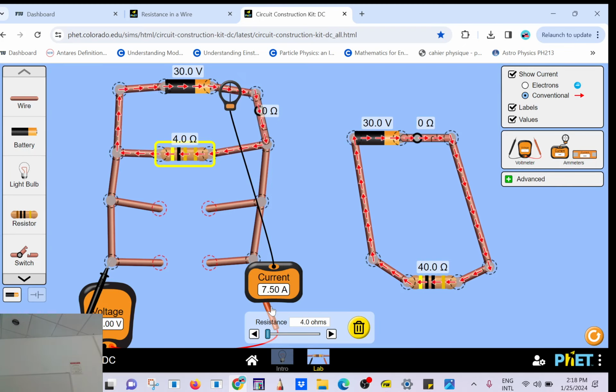But because those batteries are getting old, inside them, you have a sneaky internal resistance. If I just bought them, then the internal resistance should be 0. But as they get older, the internal resistance increases. So it means that when I want to measure the voltage now and I have a load connected to it, what do you read?